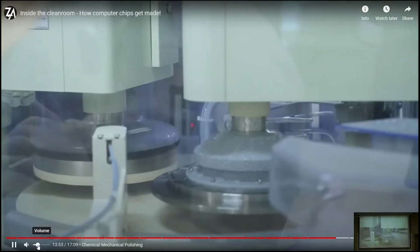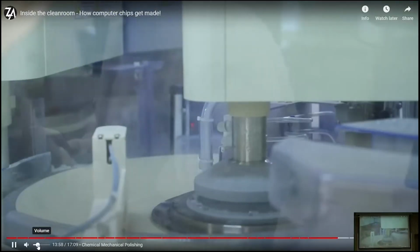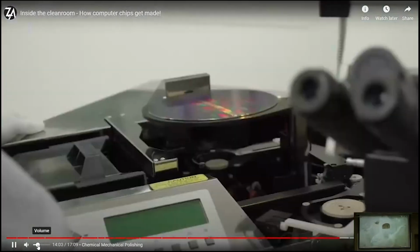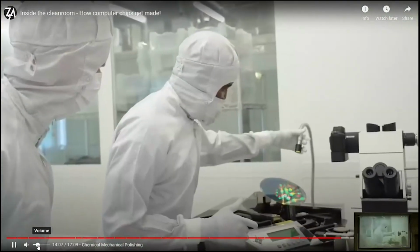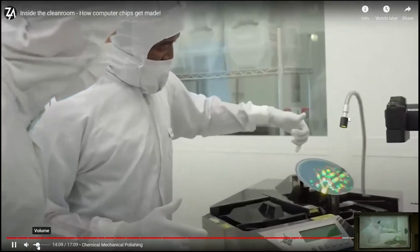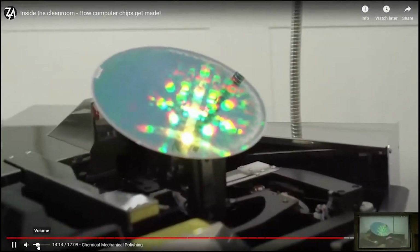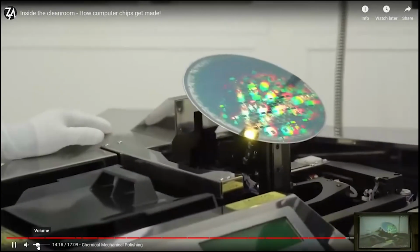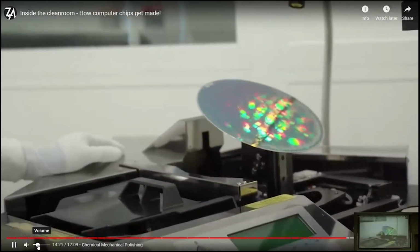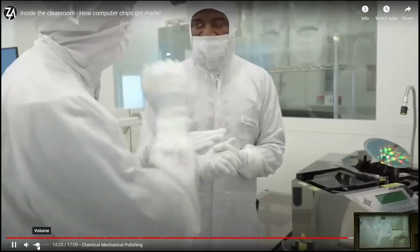All right. And then this is coming to dress the wheel again to kind of clean it. Exactly. So after using the tungsten CMP, I have to check if there's tungsten rest on it. For this particular process right now, you can see some white cloudy stuff on it, so there's tungsten on it. I have to see what to do to make sure everything is clean. It needs to go back in the machine for longer, probably. So you're aiming between not enough and too much, and you've got to get it just perfect.